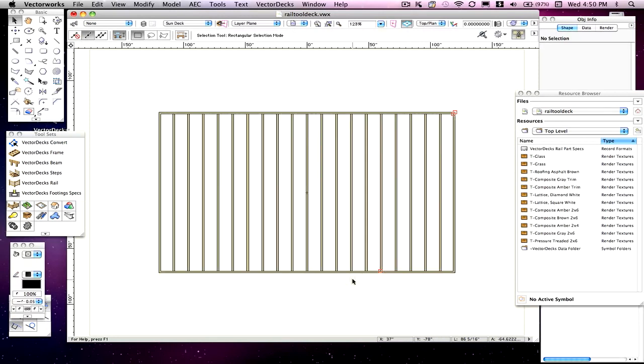And the second important thing is the rail is a polyline tool, so you'll be clicking and dragging and clicking and dragging, and make sure that's always done in a clockwise direction. It has to do with how I create the math in the plugin to produce that rail, so the outcome is what you're looking for. So clockwise direction is an important part of this.